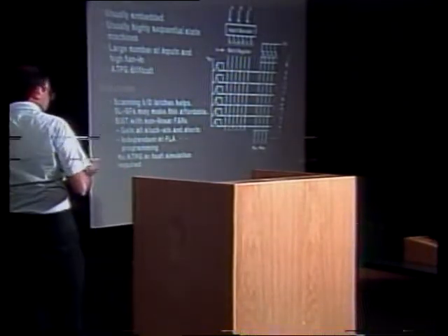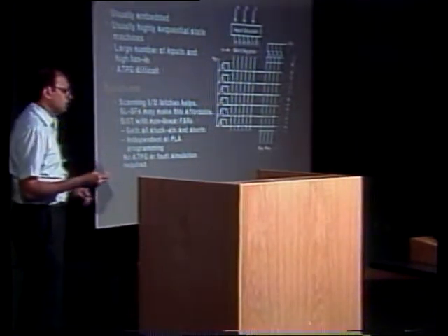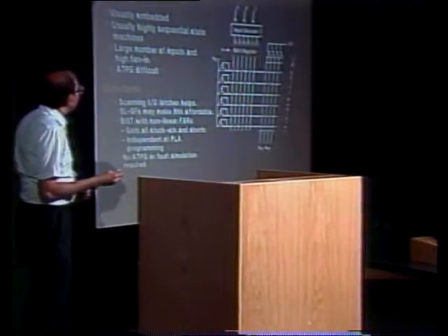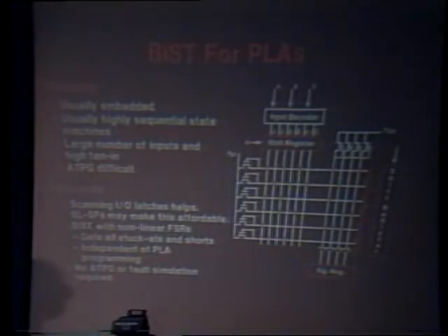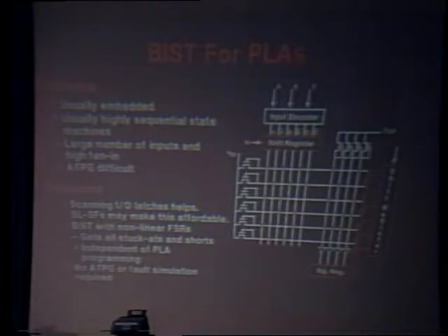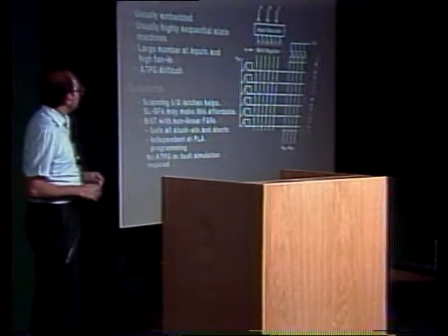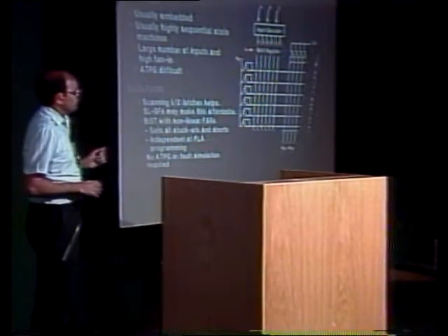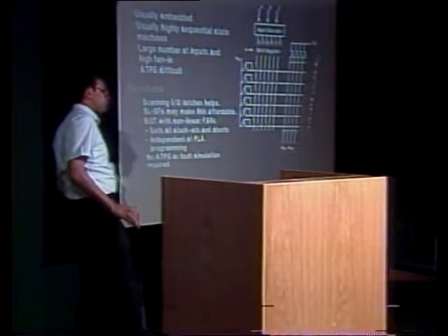What about the PLAs? We use lots of them, especially in the custom chip environment. The problems are that they are usually deeply embedded and highly sequential machines. Further, associated with them are a large number of inputs and high fan-in. And as you may recollect, Roy mentioned this morning that if you have a large number of inputs and high fan-in, then pseudorandom vectors tend to fail. Those are the failure modes over there,